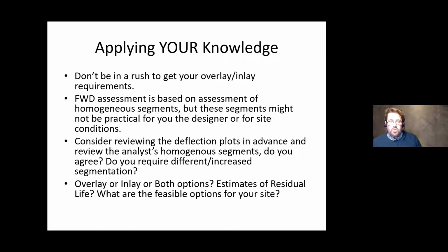But be conscious of what you can do, and consider reviewing those deflection plots in advance of getting the overlays back. When the testing is carried out, ask, can I get the plots just so I can review them myself and see, are you in agreement with the analyst?